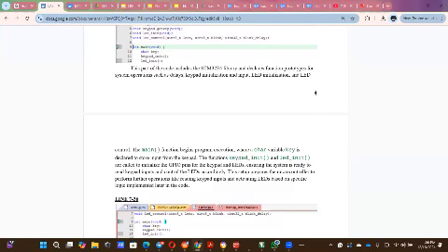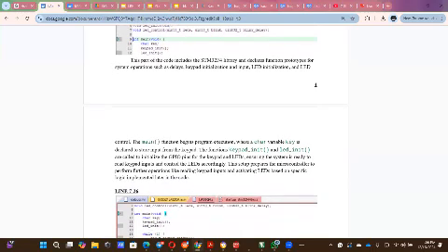The main function begins with the execution where a char variable key is declared to store input from the keypad, which is the input that we used: 1, 5, 9, and D. Then the functions keypad init and LED init are called to initialize the GPIO pins for the keypad and LED, which is to ensure the system is ready to read the keypad input and also to control the LED accordingly.